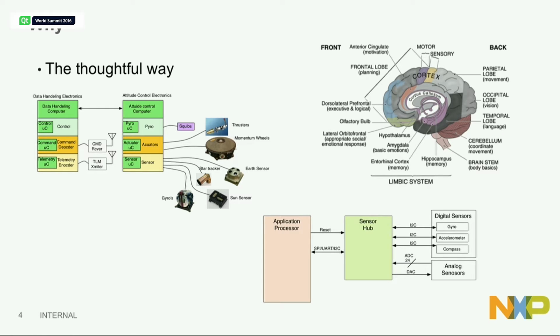So now, Apple comes out with their new phone and they announce we have an M7 now. How awesome is that? And everybody says, wow, that's cool. They don't even know what it's for or why, but it's cool, right? It's the same idea. It's got the gyros, but now they're digital MEMS ones, and then we have a sensor hub. Application processing completely off, and it can do all the sensor data calculations. It can do all the Kalman filters and things like that to do motion tracking. So all the inertial navigation can now be done in this little thing, not on the big thing, right? That's way better, and that's kind of going back to what was done in the past.